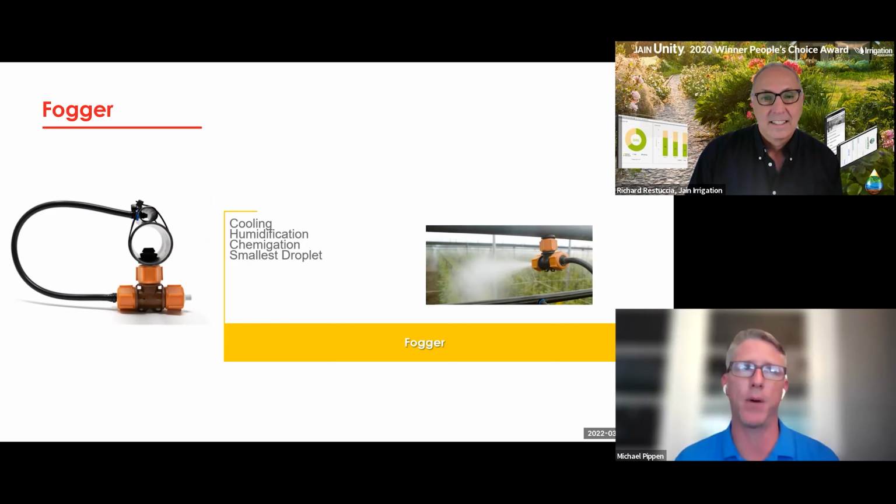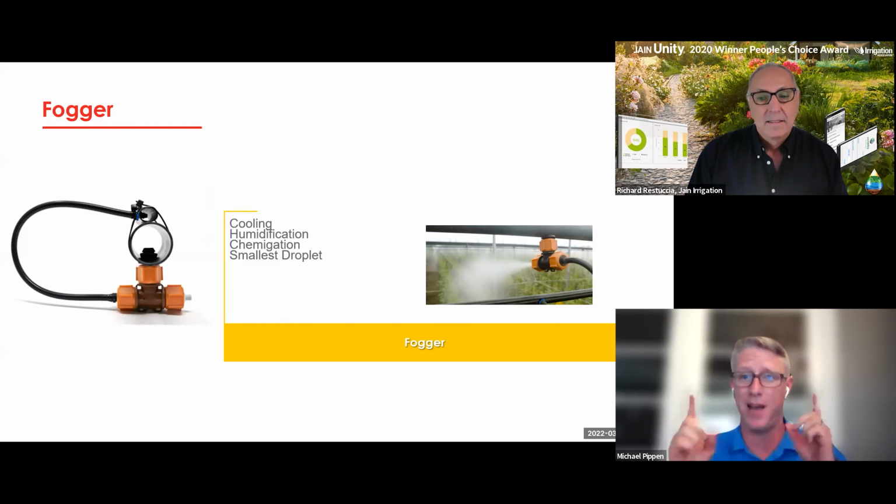So we're not running that high. We're only running about 40, maybe 50 PSI on that air pipe. So not that high, but we have a big piece of pipe because we can't really have very much variability in the air pressure. Right.